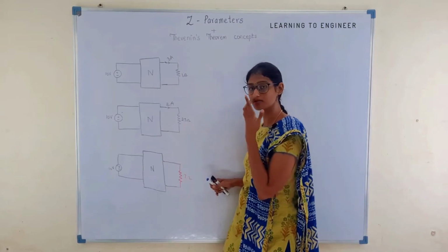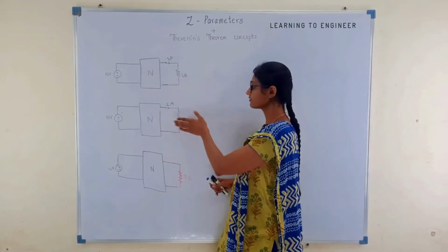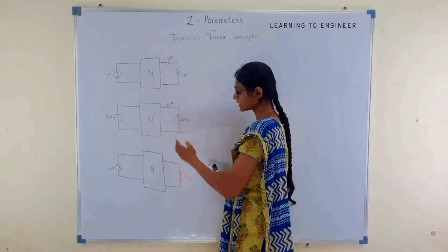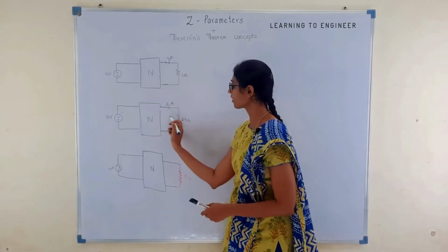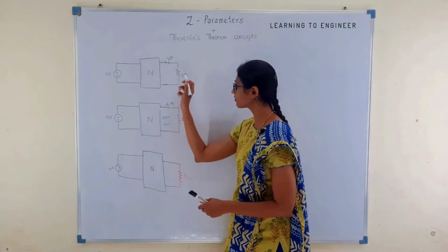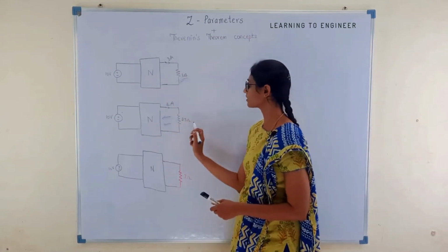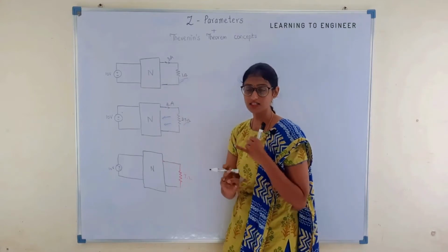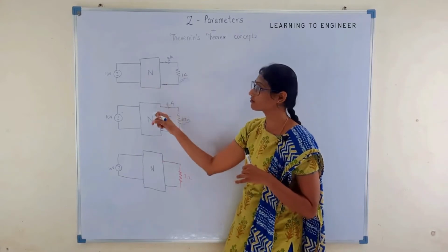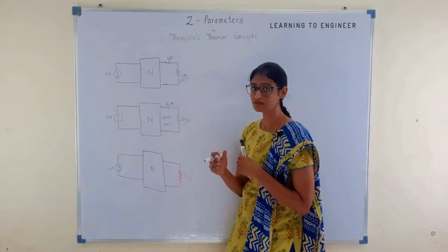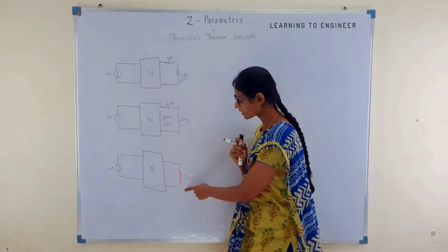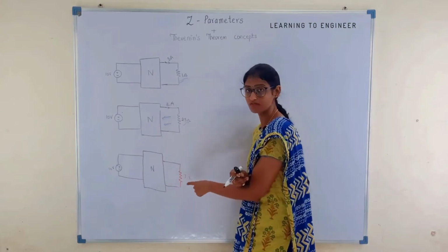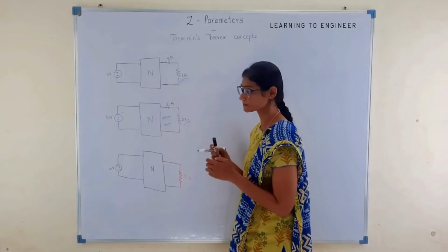Same for Thevenin equivalent resistance, because when we are trying to find out Thevenin equivalent resistance of one network, we will look at the network from the point of view of the load resistance. So, in both these cases, this 1 ohm or this 2.5 ohm doesn't matter. So, therefore, RTH and VTH are same for both these nodes. Once we are able to find out them, we can find out the current that is passing through the port 2 when we have 7 ohm resistor.